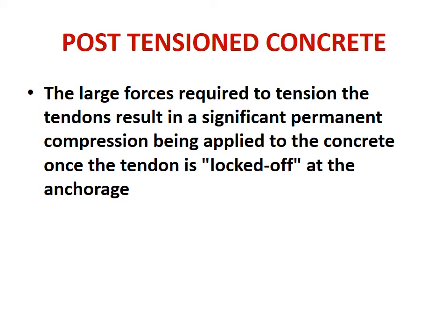So on one side this is to be locked off, and then at some part a small portion of concreting is done last, so that the concrete should be able to take up the load, and there should be no crack or no debonding with the tendons. So high performance concrete or high strength concrete is required at that.